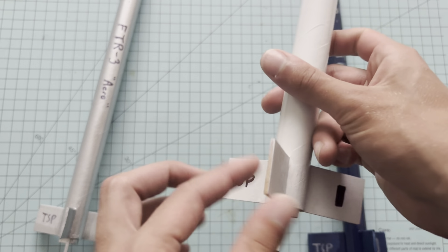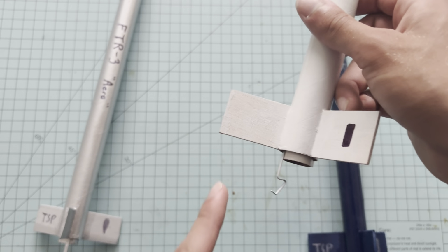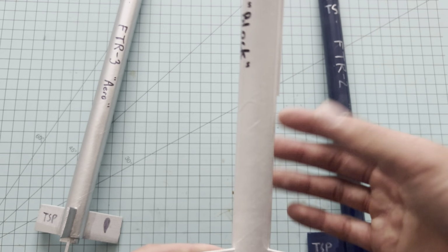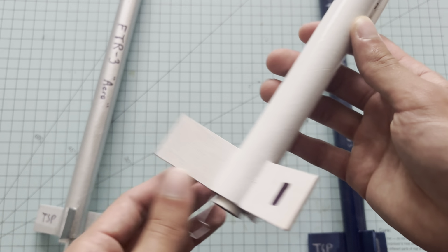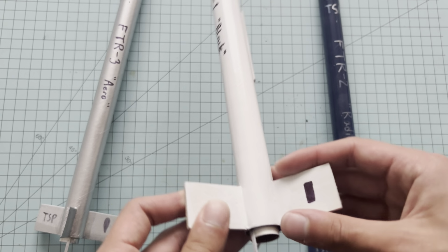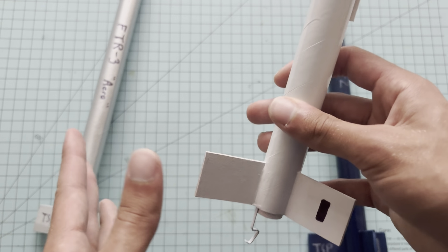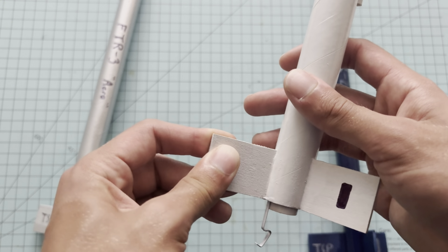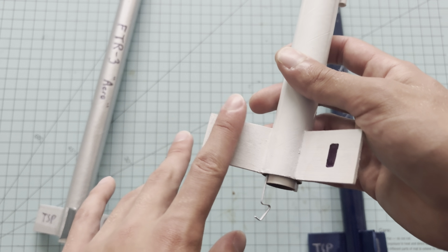Simple fins, they're made out of basswood. Grain goes this way, which is what you want, that way it's stronger. If the grain's going the other way, it might snap when it lands, but these probably aren't going to be going high enough to be at risk of breaking basswood. I think I already talked about basswood, but sorry to repeat myself if I did. What I like about it is it's a little bit hard. It's still fairly light, definitely not nearly as light as balsa, but it makes up for it by being a lot stronger. And it's also naturally much smoother in my opinion.